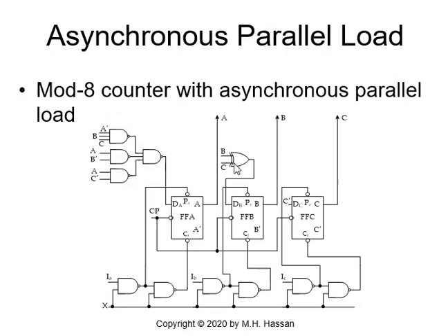If you go to the lecture Design with D flip-flops, you will find this circuit. Here we added to this circuit a parallel input data line, which is I0, I1, I2, and this will allow me to load the data with 2 NAND gates for each of those.